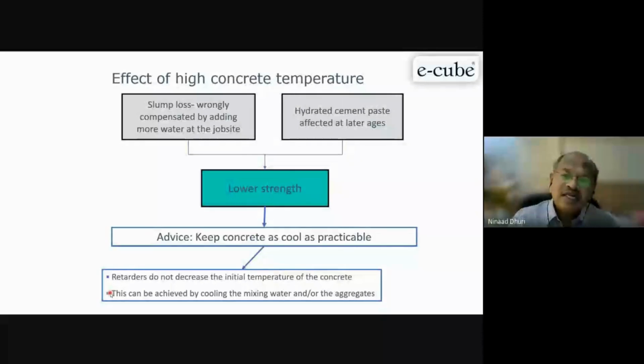In contrast, when you are working in cold weather concreting, I have to heat the materials. I can use warm water. I can use accelerators. Suppose you are working in the Himalayas or Kargil or Ladakh, where the temperature is maybe sub-zero. There normal concrete will not set at all because hydration will not take place. Then I can go for set accelerators to accelerate the setting time.